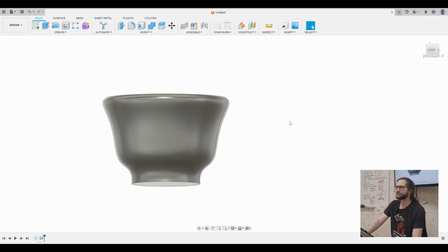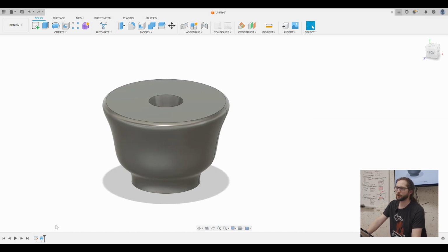So that's your two functions when you hit the revolve. It's going to ask you what profile do you want to revolve. That's your two-dimensional shape, and then what axis do you want to revolve it around. The axis is any straight edge. So it could be an edge of your drawing. It could be one of the origin axes. It could be the straight edge of another body in your drawing already. That could be interesting for some circumstances. Yeah, this is cool.